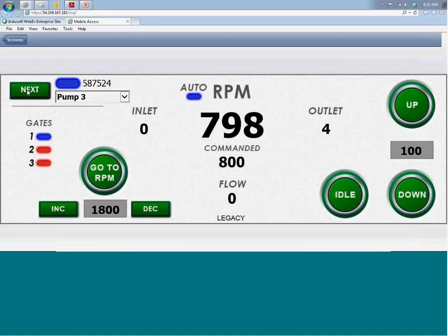We did all the graphics and everything in CODESYS 3.5. And everything resides on the HMI: all the machine intelligence, the human-machine interface, all the application program, and all the networking. So it is the network master for a CANopen and J1939 network both. So, CANopen, J1939, and Ethernet. So 2 CAN networks and 1 Ethernet network.